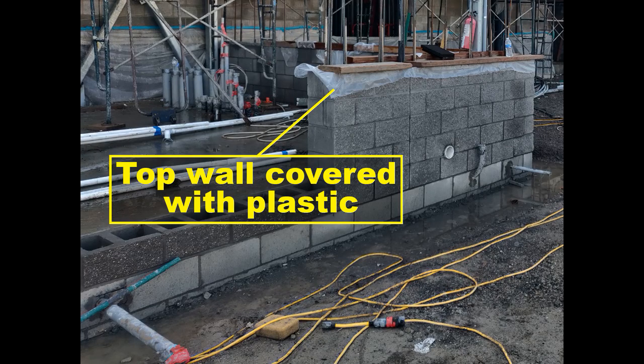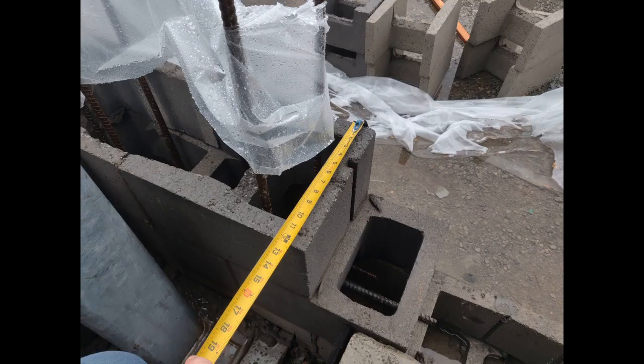Protection. Protect facing materials against staining. Cover top of walls with non-staining waterproof covering or membrane to protect from moisture intrusion when work is not in progress. Continue covering the top of the unfinished walls until the wall is waterproofed with a complete roof or parapet system. Extend covering a minimum of 2 feet down on each side of the wall and hold securely in place. Before starting or resuming work, clean top surface of masonry in place of loose mortar and foreign material.